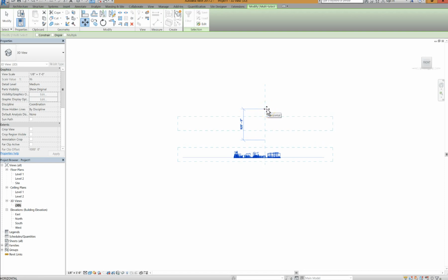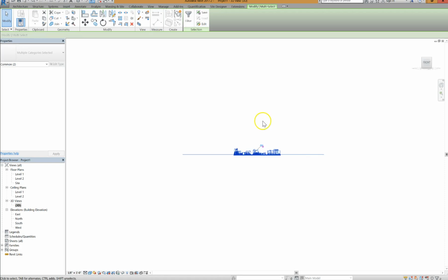And right away it wants to start moving up. What I'm going to do is type in 80.96. And then if you really want to get fancy, you do 33333. By default, Revit does everything in feet. So if I just hit Enter, that moves it 80 feet.